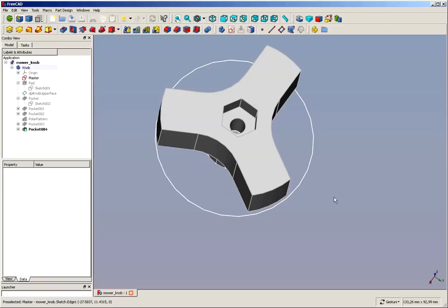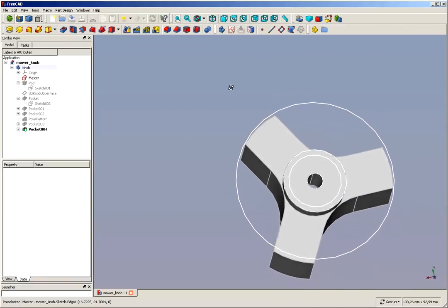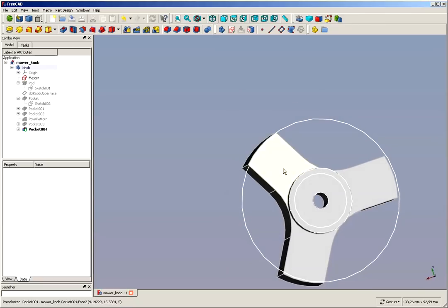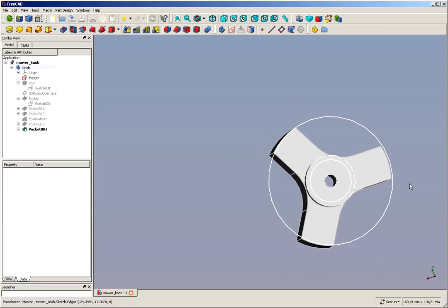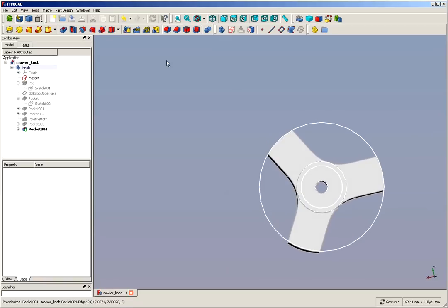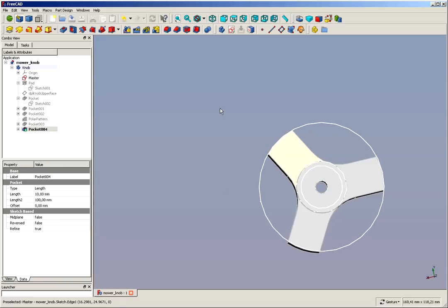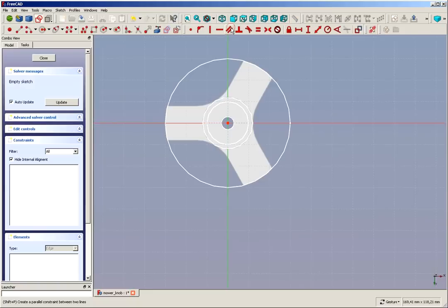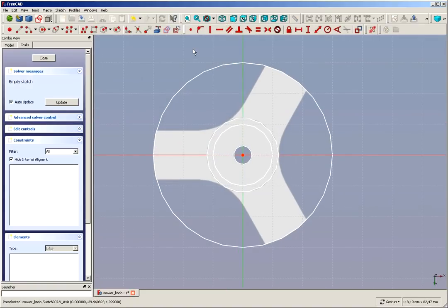One thing is, if we make that knob completely rigid, even in a 3D print with infill, it might not make a lot of sense. We could cut out a little bit of material here to make it lighter, and we do this by creating a sketch on this plane.